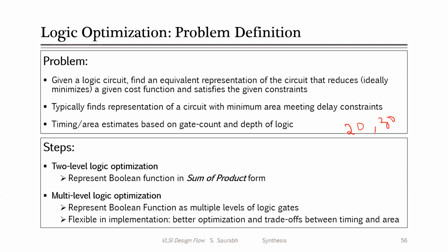So if the number of variables becomes too large, then the techniques that you have studied in your BTech courses, for example, Karnaugh maps, will fail, and you cannot apply those techniques. But you apply many other types of logic optimization. These are known as two-level logic optimization based on some heuristics, or multi-level logic optimization based on transformations, and various passes are done, or some algorithm which is basically trying to reduce the area given an initial circuit, and that is done in the logic optimization phase.